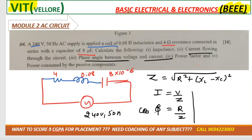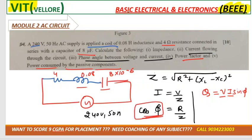Then they are asking for the power factor. Power factor you already calculated, cos phi. Then the power consumed by passive elements. Passive elements mean inductor and capacitor. Power consumed by passive components means they are asking for the reactive power. Remember I told you the three different types of power. Passive component means reactive power, that is VI sin phi. I is already calculated. If you know the value of phi, can you get sin phi? Or if you know cos phi, can you get sin phi? So now you can solve it. Easy.